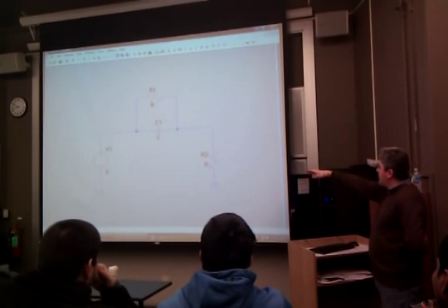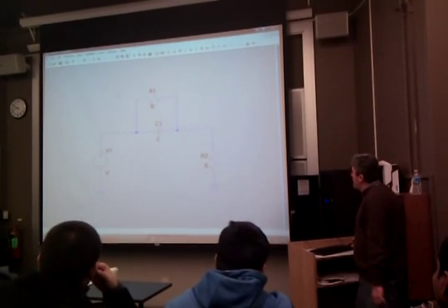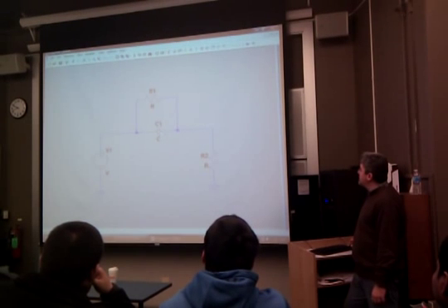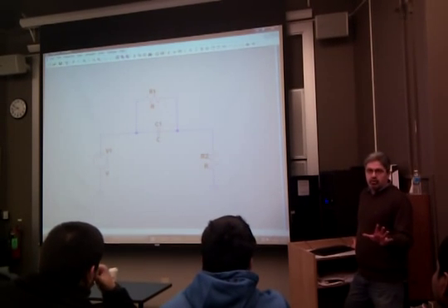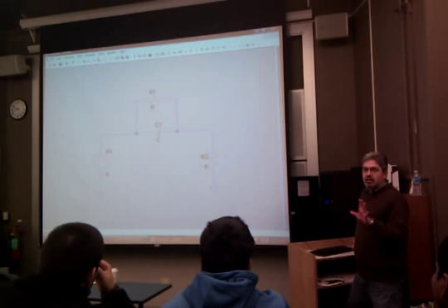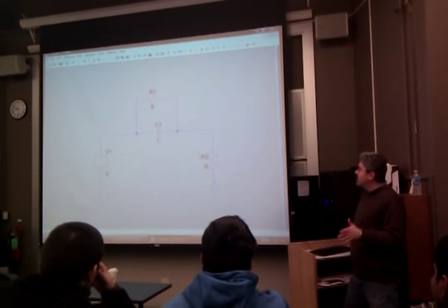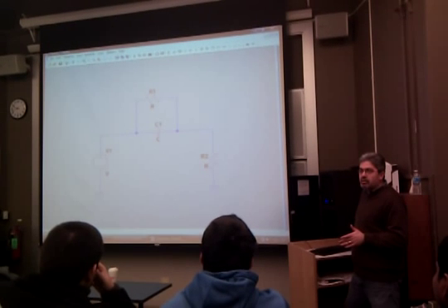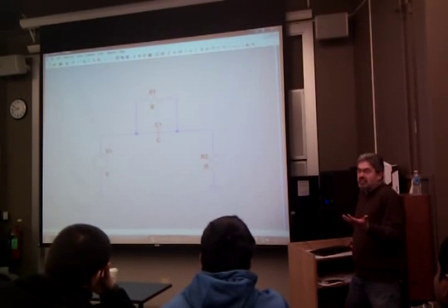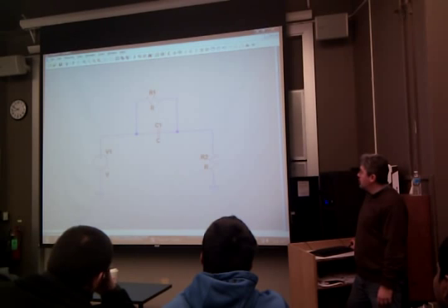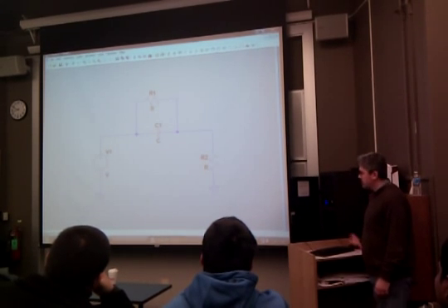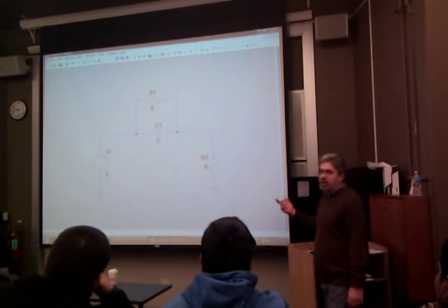But right now, I just want to put the component values in and show you what happens. What you do is these R1s and C1s and R2s, you don't touch those, right? Those are the reference designators. The reason I'm telling you that is every term, there are people who want to change these values and get errors because you can't change those. Those are not the values. The values are these. All we got to do is right click on this and enter a value.